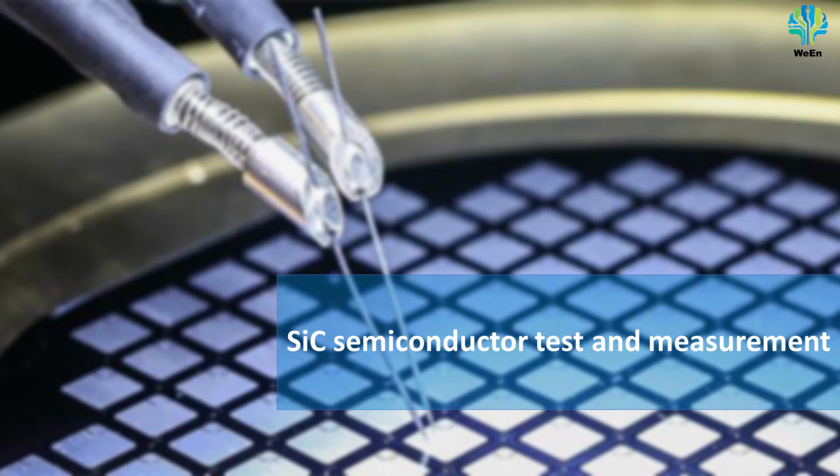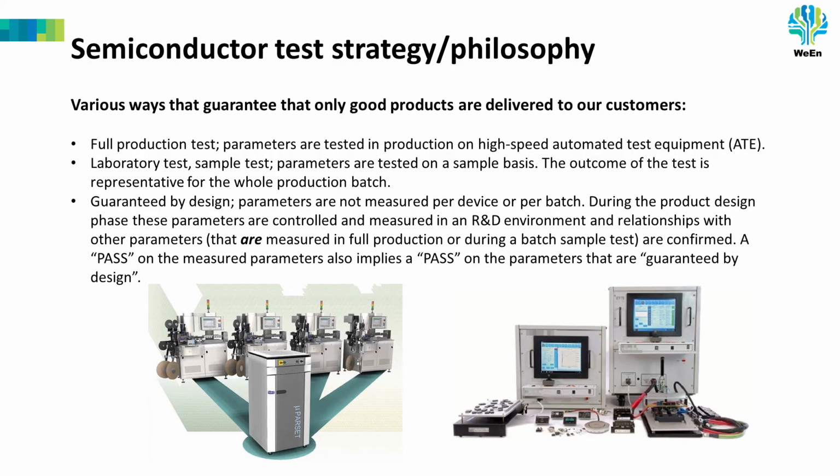Now we have a look at the test strategy philosophy. There are various ways that guarantee that only good products are delivered to our customers. Firstly, we have the full production test. A number of parameters are tested in production on high-speed automated test equipment, also called ATE. And we do laboratory tests, sample tests. Parameters are tested on a sample basis. The outcome of the test is representative for the whole production batch.